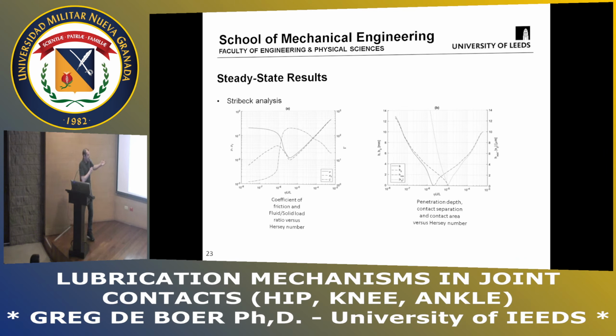We can then look at what is called a Stribeck analysis. It's a very technical tribological problem, but what this is really saying is what is the regime of lubrication. Lubrication has several regimes. If your surfaces are very far apart, there'll be no displacement, and that's called hydrodynamic lubrication. As they get closer, they start to deform. That's called elasto-hydrodynamic lubrication, where you have some separation of the bodies. And then we move towards one where they're fully in contact, and that's called boundary lubrication.